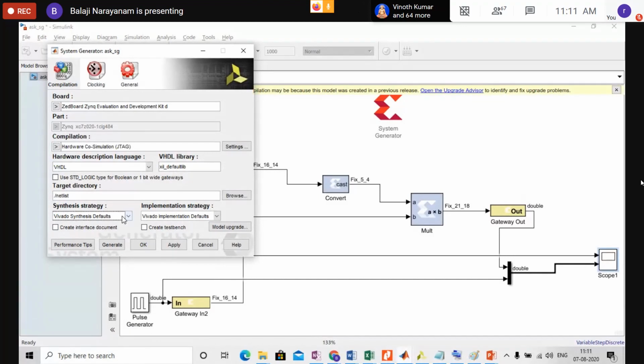Now a simple verification: I want to do the functional verification of an AND gate. What should I do? I should provide a set of input test vectors, 0 0, 0 1, 1 0, 1 1, and I should get 0 for the first three and 1 for 1 1. That is the functional verification. That is called simulation. Behavioral simulation is simple functionality verification. Now you have clarity about simulation.